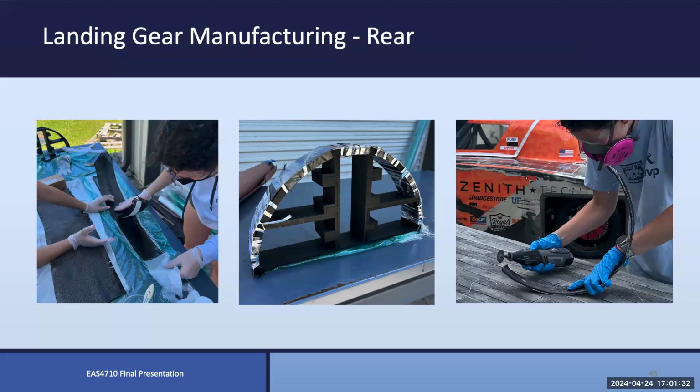So giving yourself, in the industry we might refer to this as black aluminum, where you lay up in that pattern where you've got an equal number of plies in the plus minus 45 degree and the 0/90 degree direction, and now you've got quasi-isotropic behavior, which is nice and easy to analyze and behaves predictably. You don't get weird curing effects. I think you were doing room temperature cure, so that's probably not a major issue.